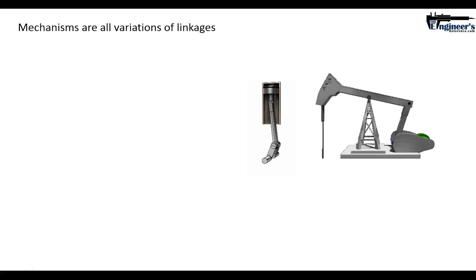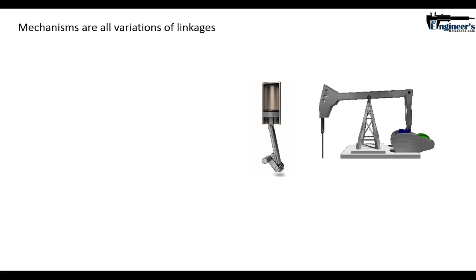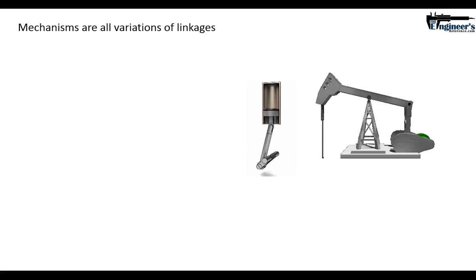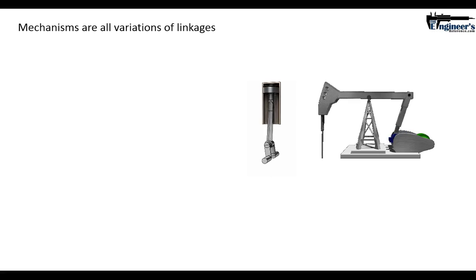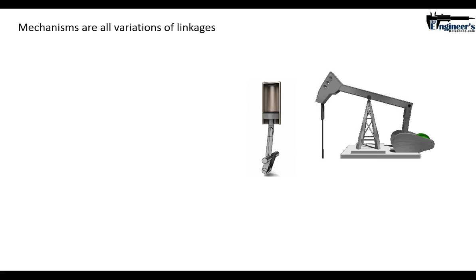Now, one way you can think of that robotic gripper is as a series of linkages. We saw it had the gripper that actually picked up whatever you're going to handle, and then a couple of rigid bars that were pinned to it, with joints that went back to a gearing mechanism. As the gears rotated, it created an output that we wanted, which was an actual gripping action. And that is the basis of most mechanisms. They're just a variation of linkages.